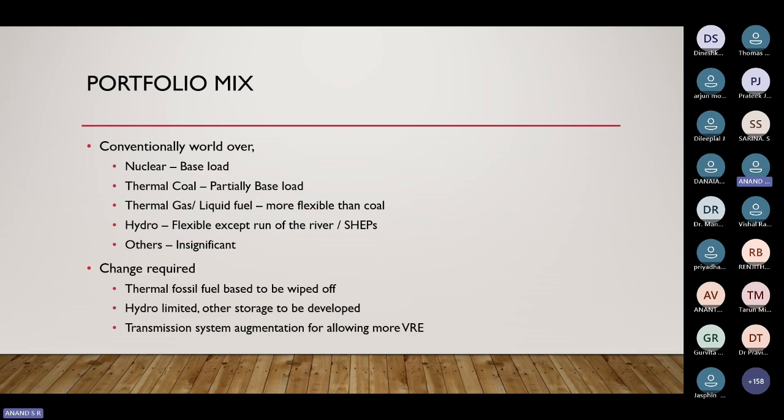We can reduce the generation, but now with some modification of the pipelines in the steam lines, it is possible that we can go to 40%, and we have already enacted a regulation that all generators should be made suitable for reducing the generation up to 40% of the installed capacity, of its rated capacity. Even after that, if we can reduce further than 40%, only then will we be able to get more and more solar energy. For that purpose, you can go for a duplicated boiler.